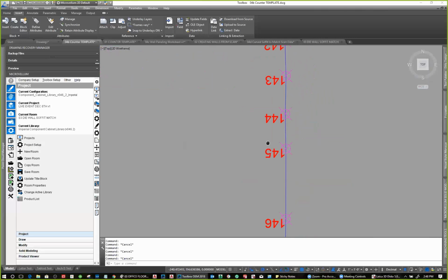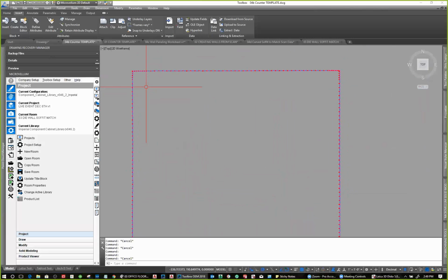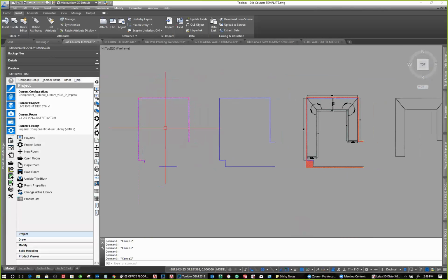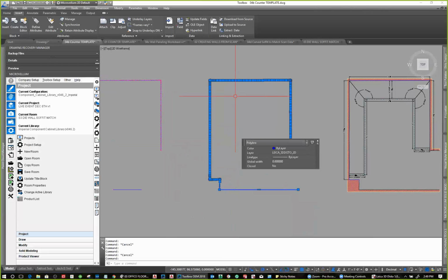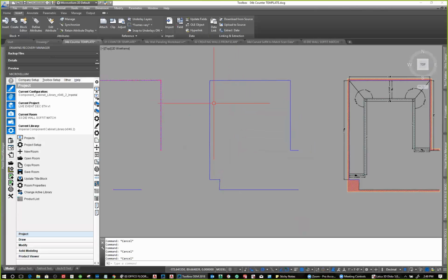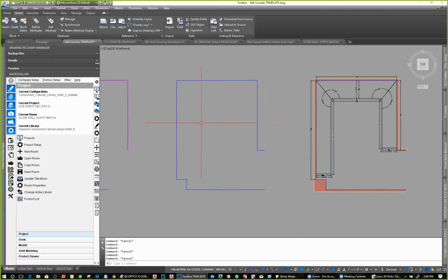And then the thing that happens, when you're looking at it in the CAD environment, is you also see it assigns a point value to each one, or not a value, but just an identifier. So this scan was about 188 points. I started over here and I just worked my way around, and this was the data. So what I did was I took the data out and I opened up the 2D file so I didn't have to bother flattening it. And then I created a polyline.